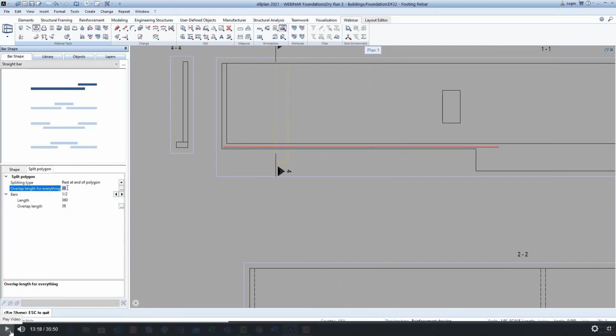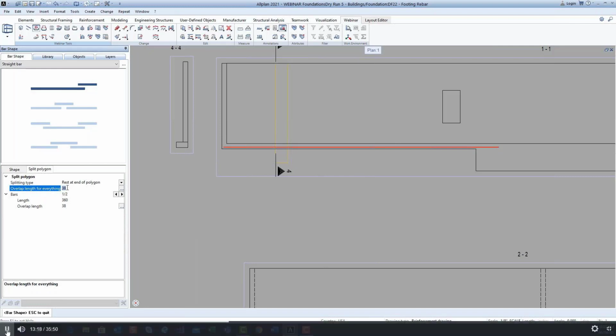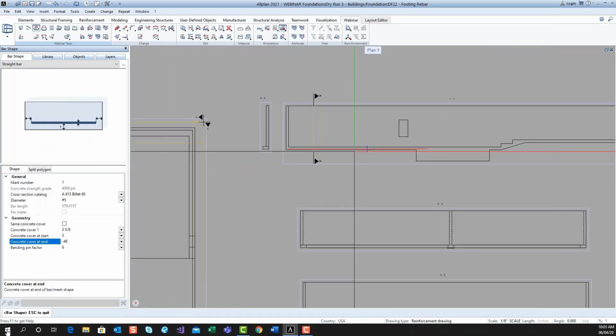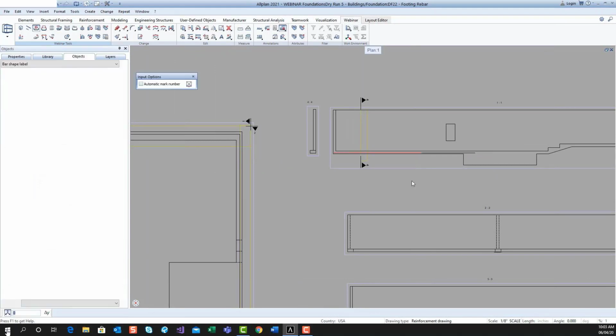What I've done is predefined, as part of this particular project, what my maximum stock length bar is. It's an overall stock length, which means every single bar for this particular one, number 3 through number whatever, I believe I set at 30 feet. So any time when we're detailing a bar and it gets past 30 feet long, it automatically knows to add another bar to not extend past that. I'm changing the lap length to 30 inches because that's what they specified. And now I've got a 30-foot bar and whatever the remainder is.